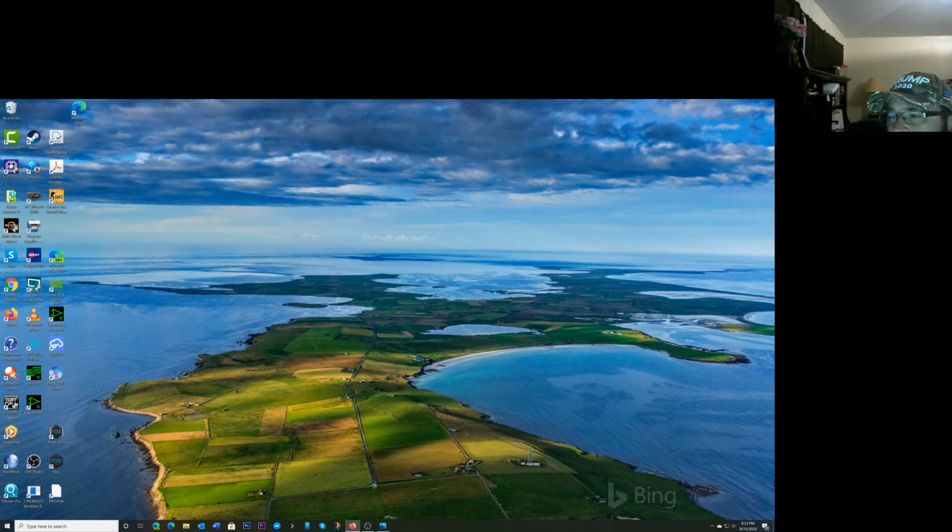So I could do maybe some other tricks. The simplest thing would be to add 2 more panels, and once it's running, have it switch those other 2 on to make the DC bus higher yet from the solar. More of a voltage divider effect, basically. It would definitely pull at least 2/3 of the current off of the solar. Plus, the solar would add another 500 watts between the 2 panels I'd be adding. So it'd be a win-win if I could put those other 2 panels on there. I just have to go 100 bucks each. It's worth it.